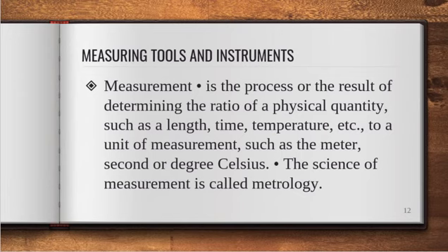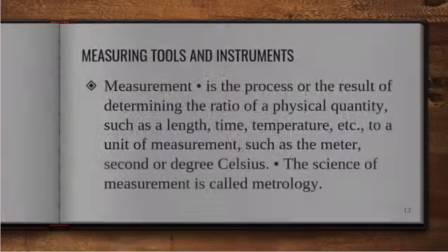It will make your work faster and even easier without going back and forth because of the wrong choice of tools. To understand it more, a precision instrument like a vernier caliper is not as good in getting the diameter of an oil pan, for example. But getting the diameter of a bearing or the thickness of a shim using this kind of precision tool is much better. So see, there is a proper measuring tool for each equipment.